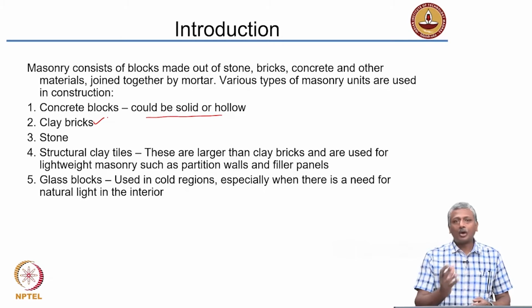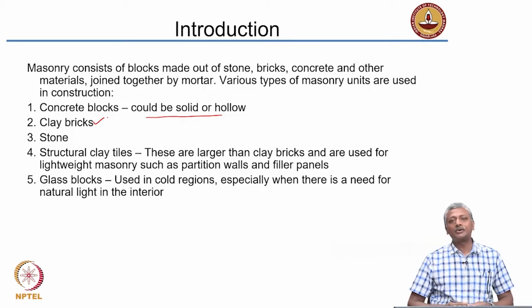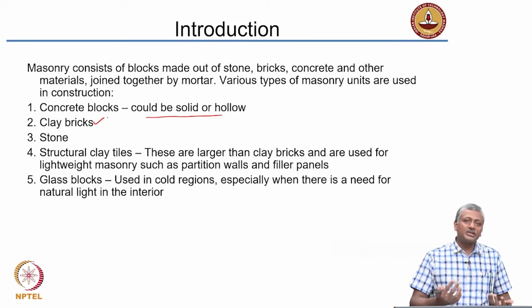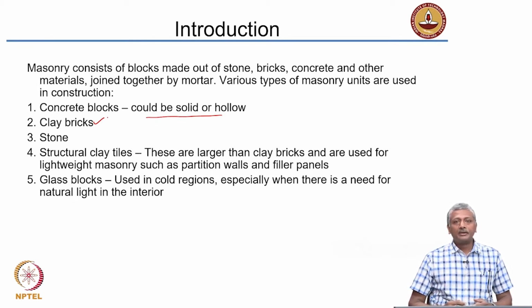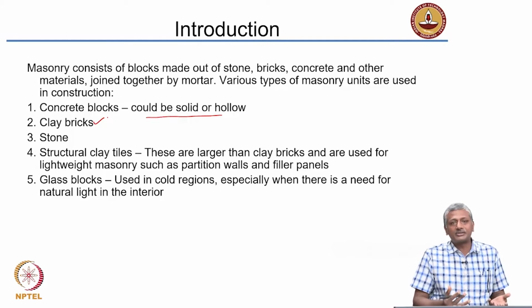Okay, so a lot of these designs are obviously the domain of architects, which civil engineers typically don't really design or engineer masonry structures. And that sometimes could be a problem, especially when you talk about earthquakes. If you don't engineer masonry structures well enough, in an earthquake there can be very severe damages. In many of the earthquakes, the structures that completely collapsed were the ones built with masonry, and that's because they were not engineered, they were simply constructed.